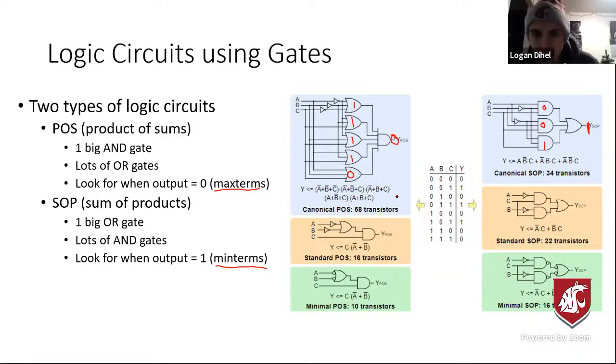I think the easiest way to do this is to go from here to a K-map, then go from the K-map to a new circuit. It's really hard to visually see what's going on. But what I do here, I look at this term. So this one is A naught or B naught, right? Or C naught. So this is the first term. And you see that right here, right? The A naught or B naught or C naught.